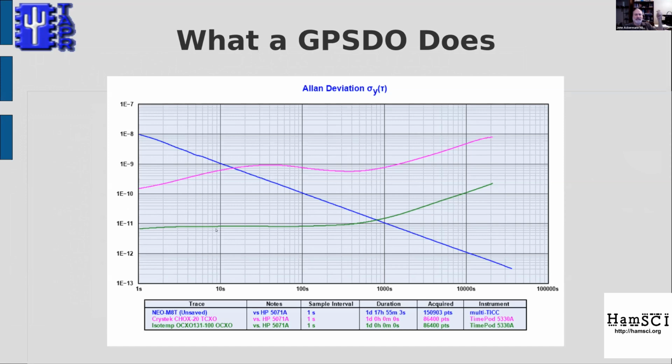Well, what I want to do in a GPSDO is have a control loop. It's typically a phase lock loop that has timing constants, so that I get this performance in the short term and this performance in the long term. And you can see from this that depending on the quality of the crystal oscillator, I have different time periods before that intercept point happens. So by choosing the crystal oscillator, and to a much more limited extent by choosing the GPS, I can design for different levels of minimum performance across any measurement time. That is the key challenge and what we need to understand.